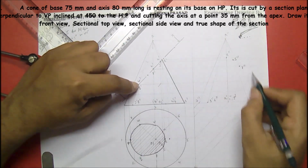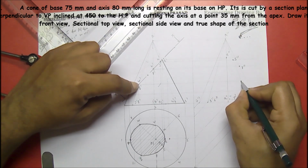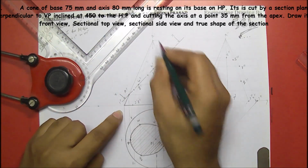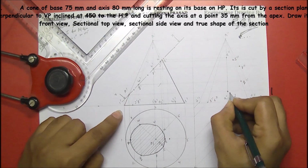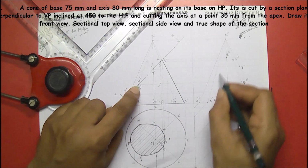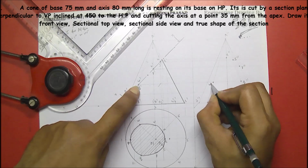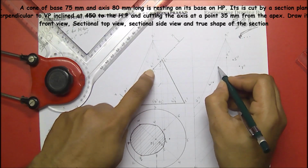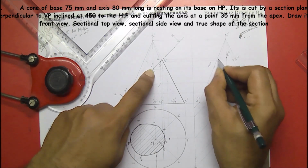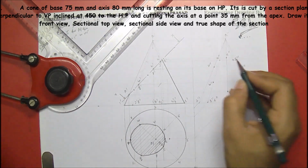And coming to Q would be falling on 2 and 8. This is 2 and 8. Q double dash. Next, P would be falling on 1 and O1. This is 1 and O1. This is P double dash. Next, coming to W will be falling on 8 and O1. See here, W double dash. And V would be falling over here, V double dash, and next would be falling U. So with this point, you can finish off the section portion of the side view.